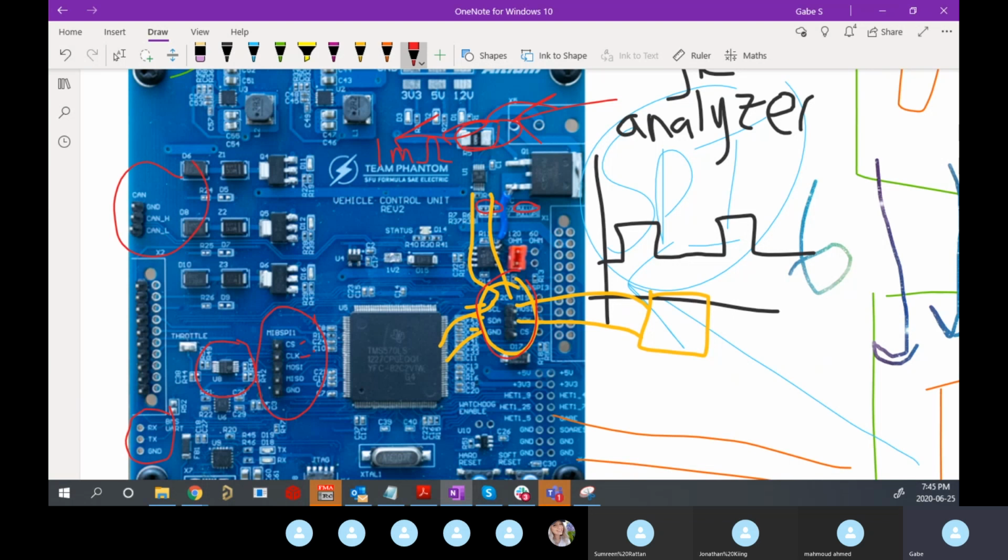So it's really important to design your board to be able to be tested so you can figure out what went wrong with it. And to be honest, everything went wrong with every single communication we did when we started writing code for this board. It's just really hard, especially the first time you're doing it. Everything will go wrong. And you never know if you did the layout wrong too, right? You may have routed a pin backwards or connected the wrong address pins to ground, maybe connected them to a different pin, so you have a different address.